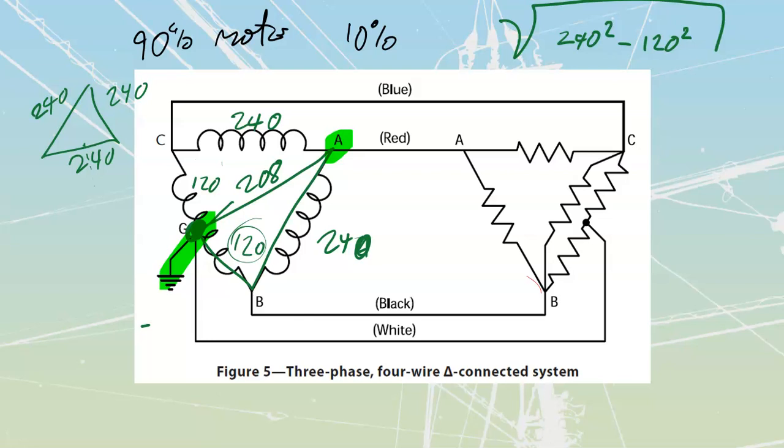Very dangerous, because if you as an electrician walk into some place, you got a 120 volts piece of equipment and you hook it up onto a three-phase panel, and one of those legs is actually 208 volts above the ground, A, there's a lot of danger to you accidentally just touching it, and B, that equipment is just going to blow up as soon as you turn that thing on, and you have potential for arc flash fire and everything else that's going to be associated with it.